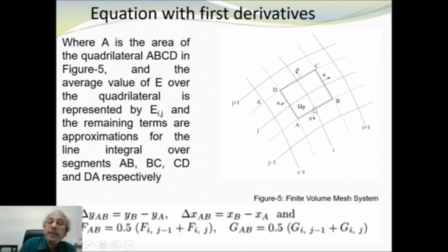So delta YAB we have seen, delta XAB we have seen, because we'll be taking the projection of this mass in the x direction. So the projection of mass which is passing through it in the x direction, and in the y direction. So rho U will be multiplied by delta YAB into 1, and similarly rho V will be multiplied by delta XAB into 1.